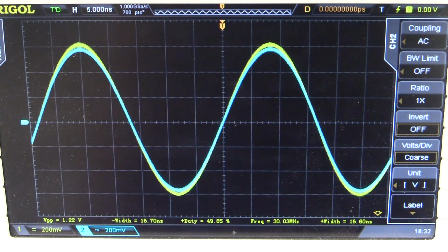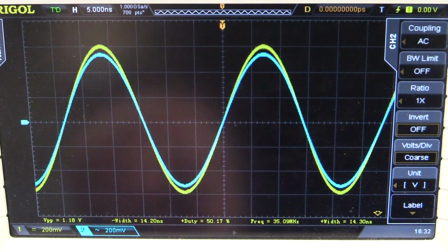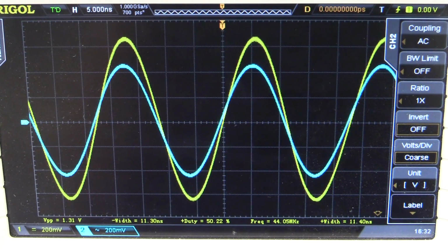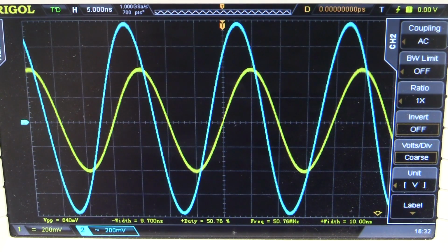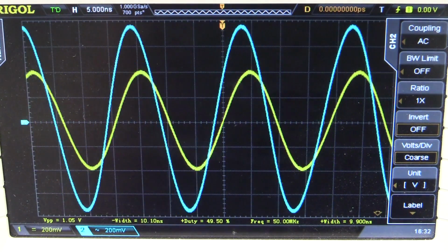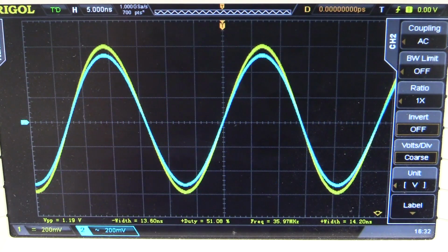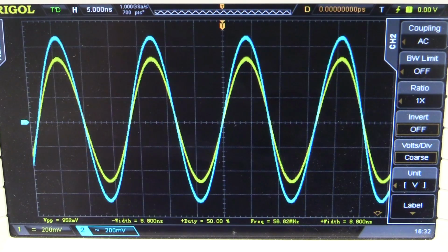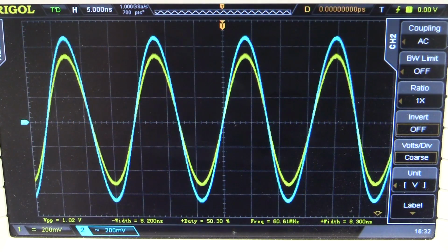So with those two similar coaxes, and if you don't terminate the inputs like on this Rigol scope here, look what happens. I mean, we're at around about 35 megahertz, and not only can the amplitude change, but then the phase can drastically change as well, and then they can swap over and do weird stuff like that at a particular frequency that is going to change with the impedance of the coax you're using, the length of the coax, and the reflection and the load being reflected as well. Yes, this is all transmission line stuff.